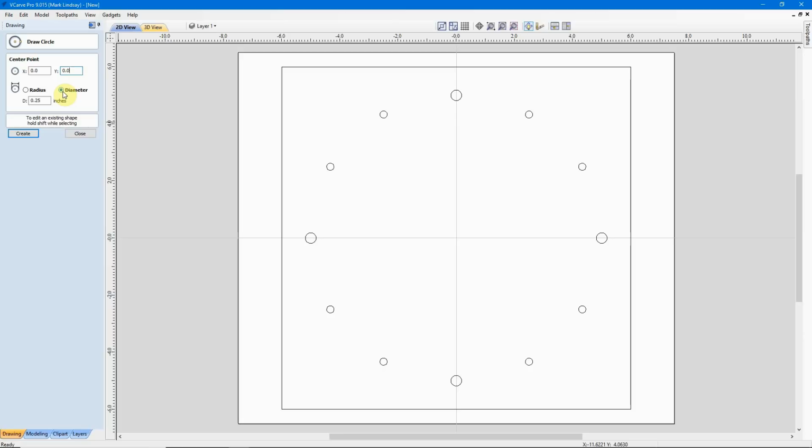And I want the diameter to be just a little bit larger than 3/8. So remembering from when I converted 3/8 a second ago, I know it's 0.375, and I want to add about 5/1000ths to that. So I'll go plus 0.005, then tap equals.